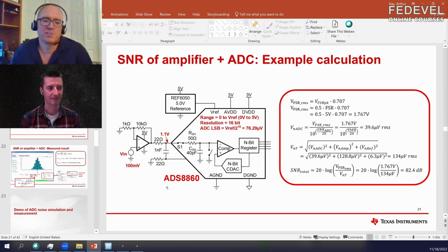Yeah, that's the difference, I would say, between extrinsic noise and intrinsic noise. With extrinsic noise, it depends on the coupling mechanism, the shielding, the intensity of the source, the distance between them. There are a lot of variables that impact that. It is possible in some cases to simulate it, but it's pretty difficult. With intrinsic noise, the simulations are actually really accurate as long as the model is accurate.